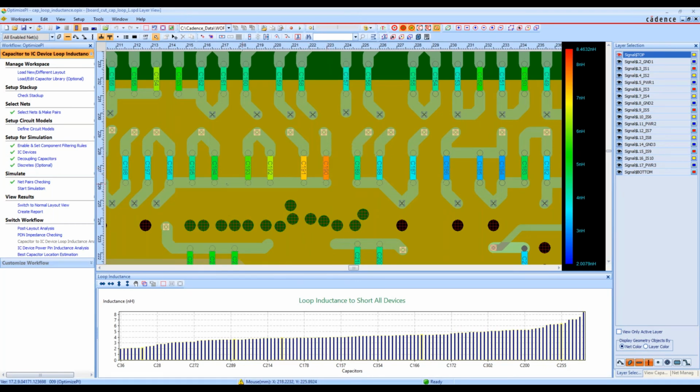And this one we decided to share a via for all these decoupling capacitors. Just draw a line between them on, I believe, the bottom layer is where they're mounted, and then use the via to connect. I guess this is power too. So connect to their power right there afterwards. Instead of bringing it out individually, we've kind of chained it along and drawn them all together. So that saves holes in your plane.